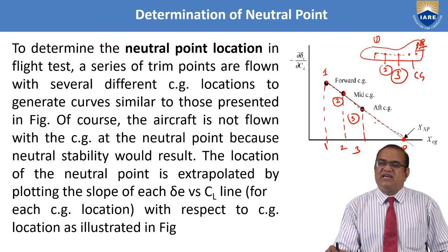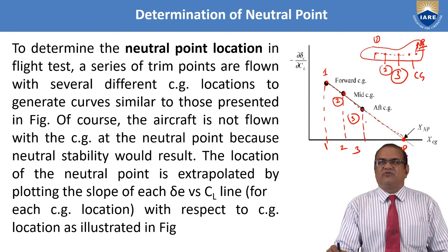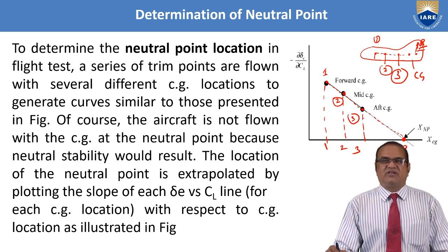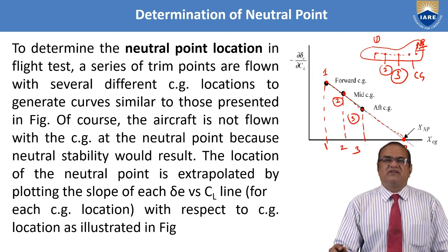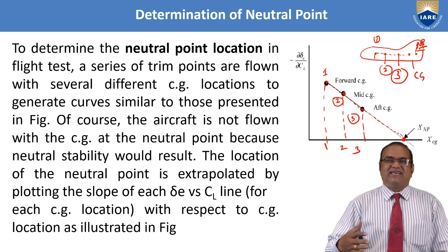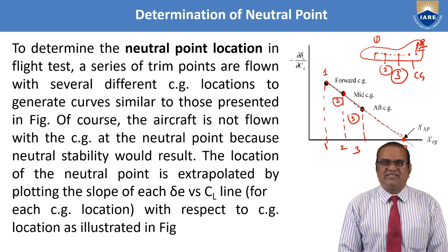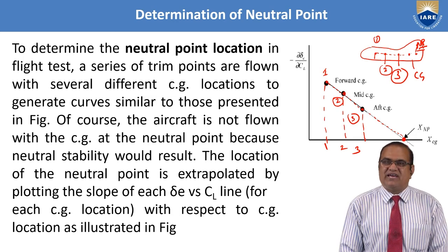So in this way, we can find out the location of the neutral point, which is very important to understand the stability of the aircraft. And every pilot is instructed in their instruction manual to follow this condition. And as an aeronautical engineer, we have to get these points for the design aspect of the aircraft.